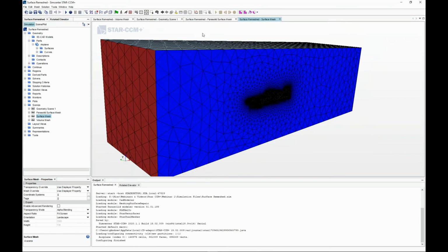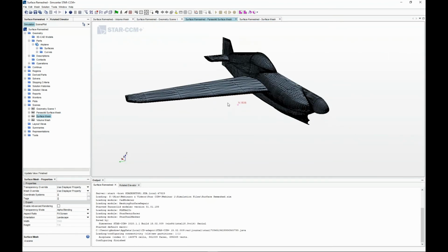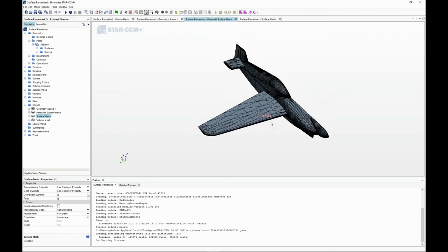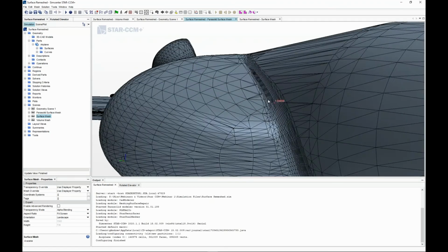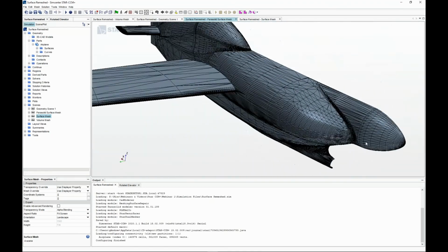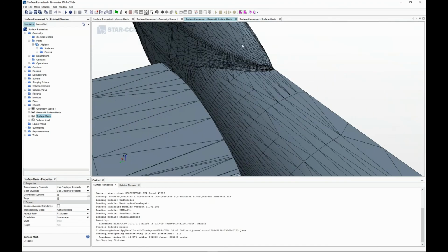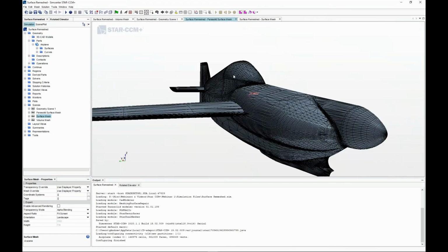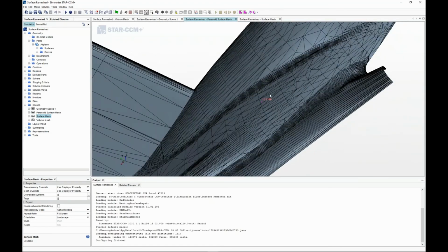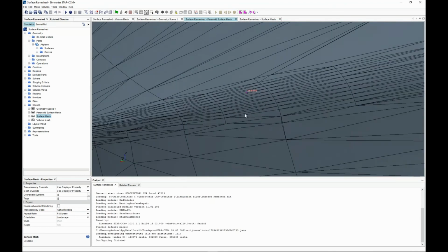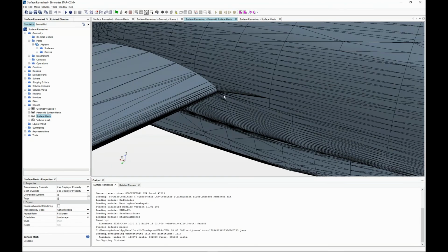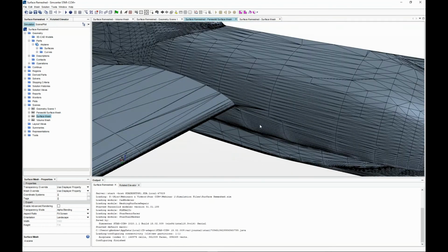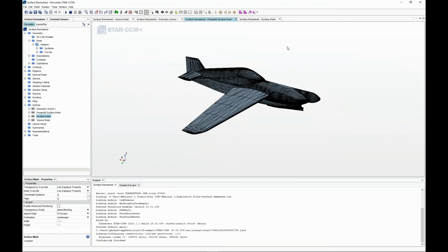Okay, so let's look at the surface mesh from the Parasolid. Again, it's the simplest way for the Parasolid engine to represent this geometry, and clearly you've got some really jank elements or cells that if you just straight up volume meshed the domain using this mesh, it would probably just not even work.